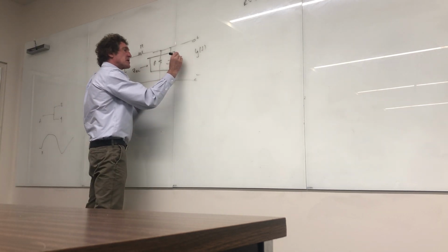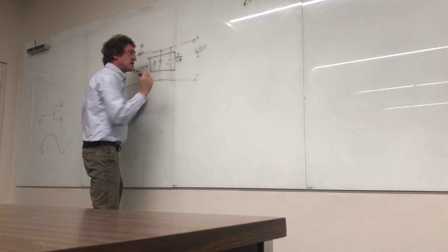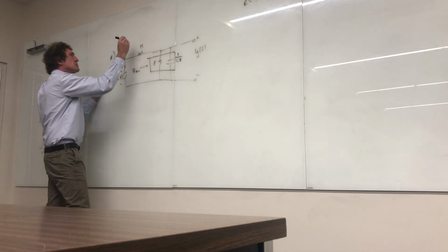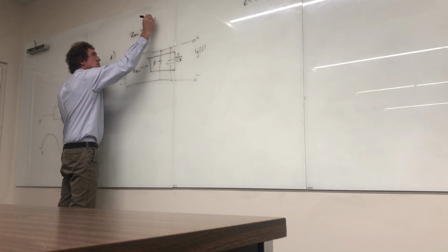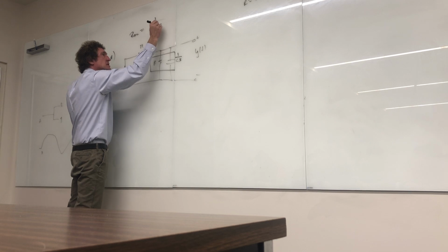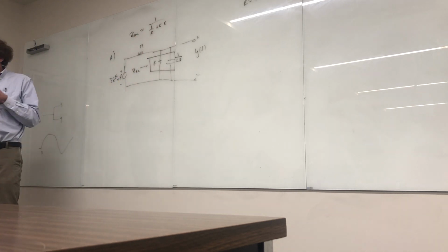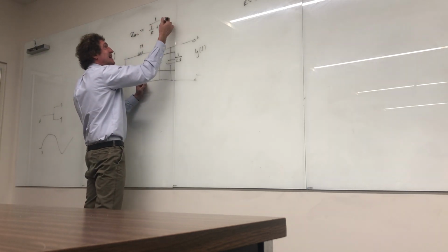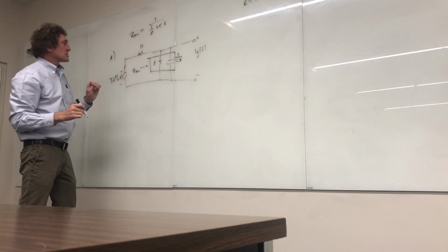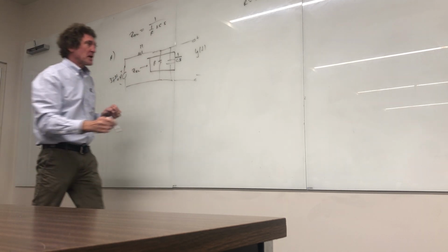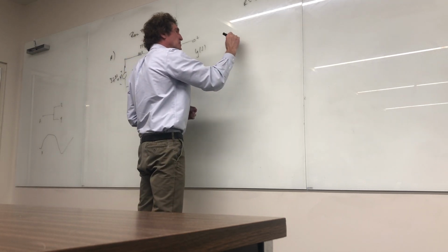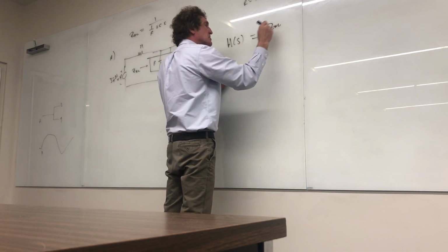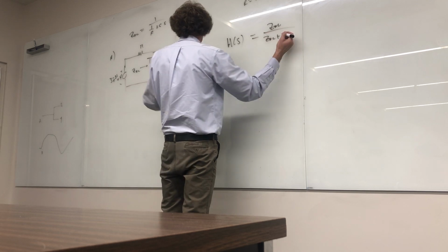And then I know the impedance of the capacitor is 1 over SC, or CS, right? Now with that, I'm going to just take that as ZRC, put it here. And that's equal to 1 over R plus CS, because it's 1 over the first impedance plus 1 over the second, correct, class? Then I take that, and now I'm going to leave that alone. And now I'm going to say, if this is ZRC here, my transfer function, and that was the homework on transfer functions, H of S is equal to the output impedance ZRC over ZRC plus R.